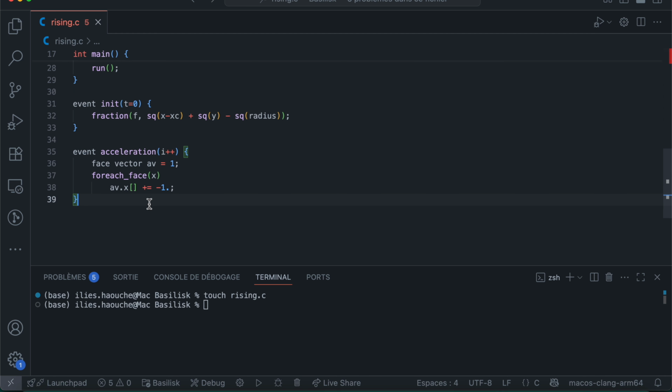Okay, so just here is the gravity. To include the gravity, you just need to introduce another event, the name of your event, and when you would like to include the gravity. So here it means I would like the gravity at each step. Here, as it's a dimensionless number, I just set up the gravity at 1, and it's in the x direction, be careful because it's axisymmetric.